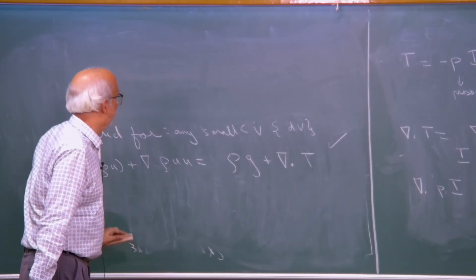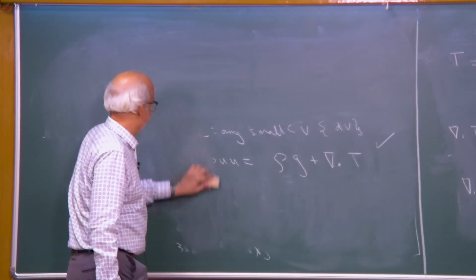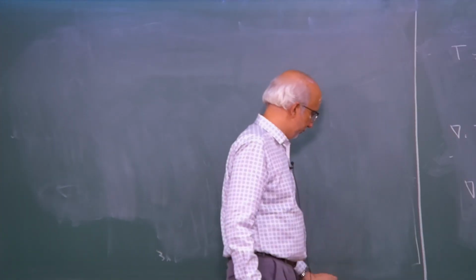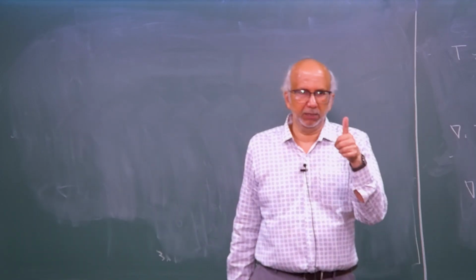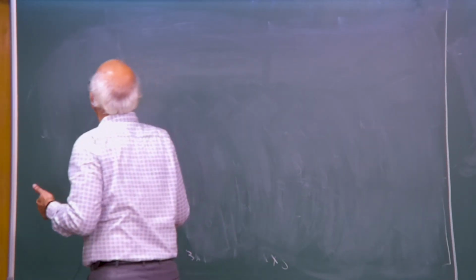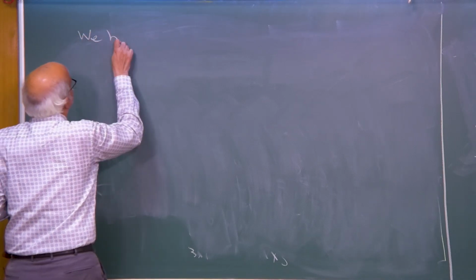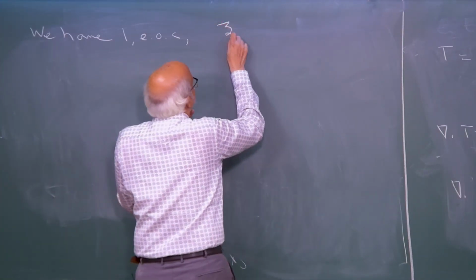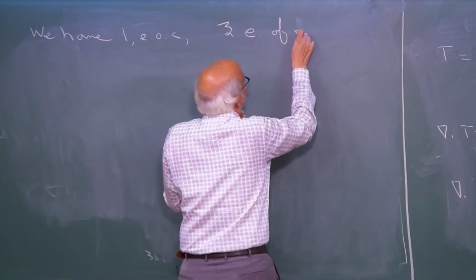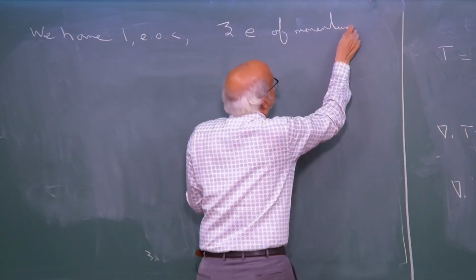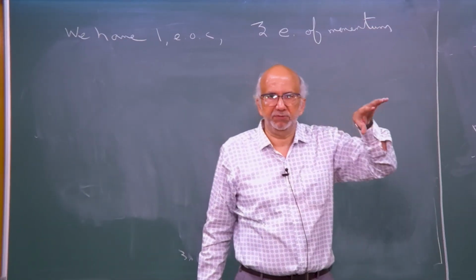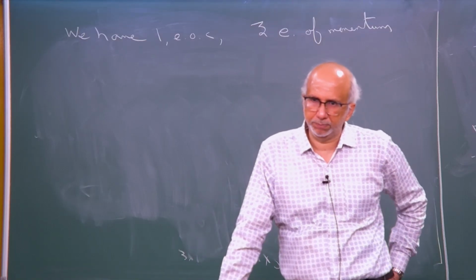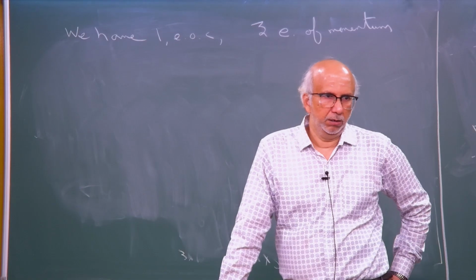One thing which we want to do is realize that the equation of continuity is a single equation. So, what do we have now? We have one equation of continuity and three equations of momentum or Navier-Stokes. Why 3? Because I have 3 directions. It is a vectorial equation. I have to write it for every component. So, totally 4 equations.